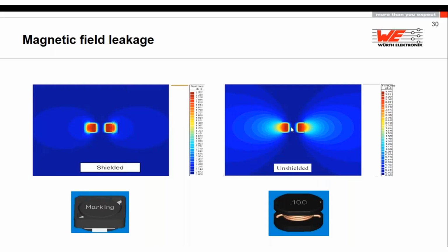It has an infinite air gap. The air gap of the shielded inductance is on the top and the bottom. We need this air gap because we don't want to saturate the inductance. But if you look at the magnetic field generated by a shielded inductance, the big magnetic field will not take the air, because air is not so good a magnetic conductor. It takes this way through the shield and comes back, but it will have some leakage anyhow.